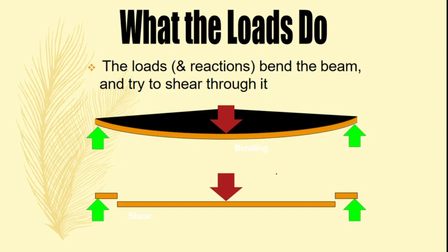Okay, if we consider the rigidity or stiffness criteria in the design of a beam, then we have to consider the deflection and slopes to design the beam. In our case here, under the strength criteria, we consider the maximum value of shear force and bending moment. Why do we select the shear force and bending moment to design the beam? Because there is a chance the beam will fail under the shear force and bending moment.